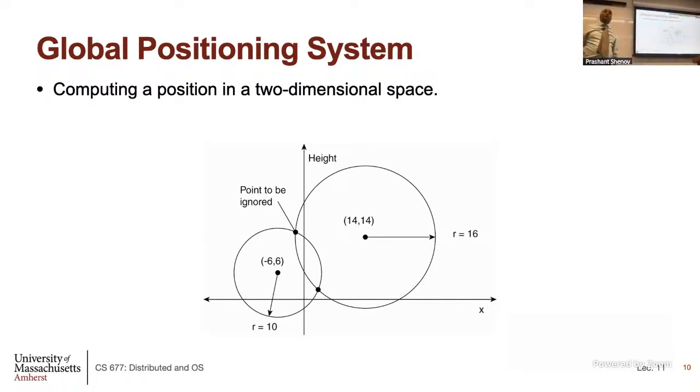Okay? So now we can repeat this, and let's say there's a second satellite, which is now at some other location. We'll call it x1, y1. You repeat this process with that satellite. It's going to send a broadcast. You'll find when the broadcasts were received. You'll take the difference between the timestamp when it was sent and the time it was received, and you know the speed of light, so you know the distance to that satellite, d prime. You will now localize it to a second circle, because you are now on a second circle with that second satellite as the center. Now the receiver is at a single location that has to be present on both of those circles. So that's how you're going to localize.